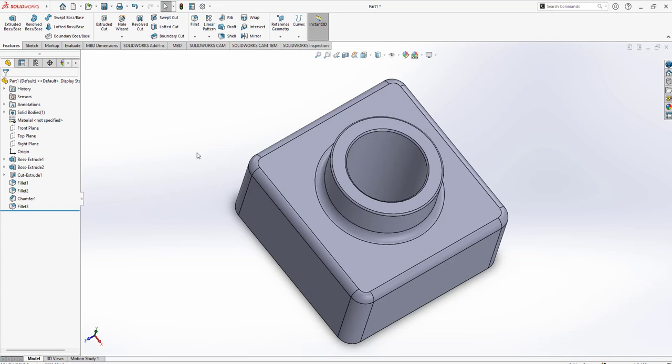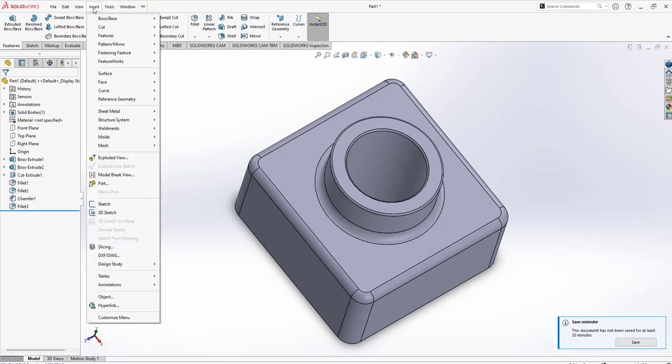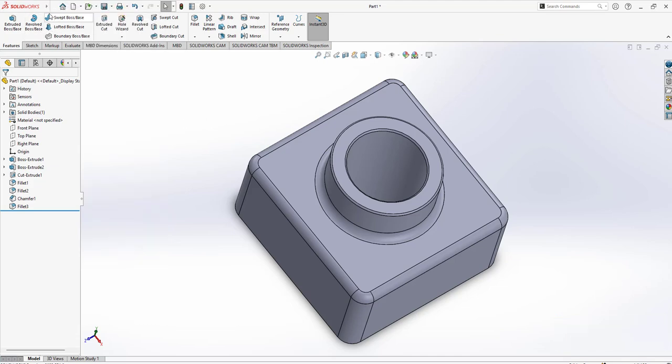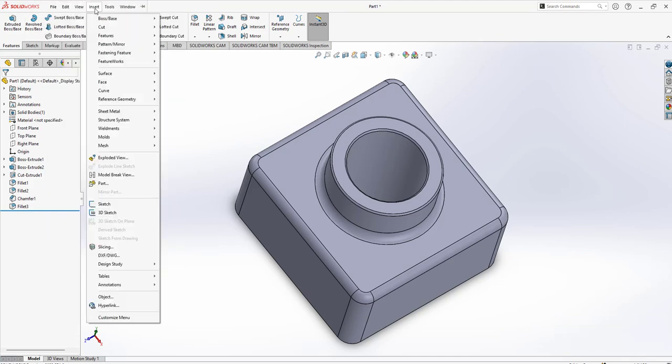We can shift to the SolidWorks design table. In order to insert a design table, one of the methods is to go to the Insert button under Tables. You can select Excel design table.